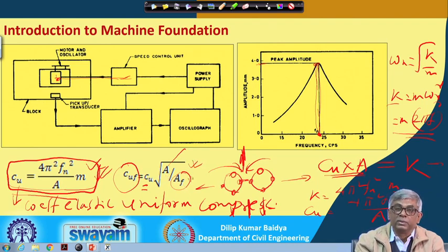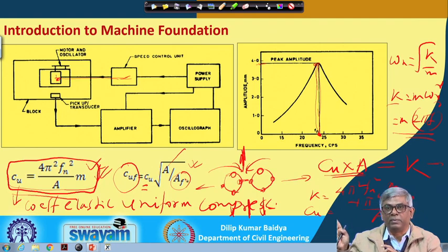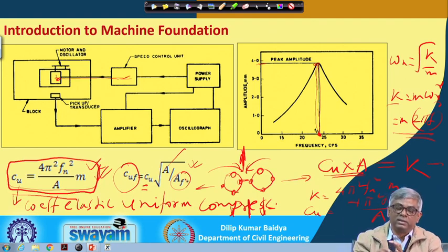So, like that it has to be corrected. If the foundation size is 2 meter by 2 meter, and actually you have tested, suppose, 1 meter by 1 meter, but your foundation size is actually 5 meter by 5 meter, then it has to be corrected taking AF equal to 25. But I have given an extreme example. Actually, if your foundation size is too big, more than 10 meter square, then AF to be used as 10 meter square.